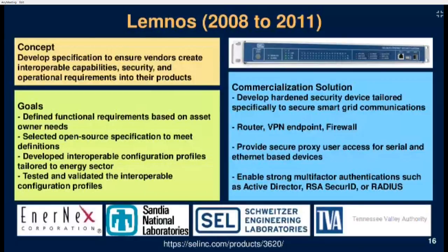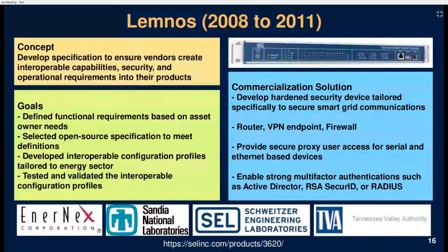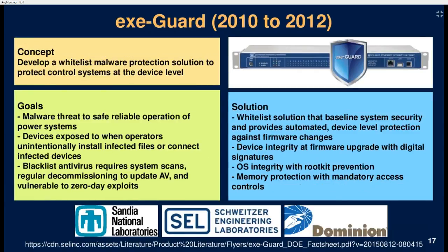My favorite example of this involves combining the centralized access solution with a one-time password. So you type in your password and the 6-digit one-time PIN, and now you have access to the relay. Then the 3620, within the physical security perimeter of the substation, would telnet into the relay. I would say this is, besides SDN, one of my most favorites.